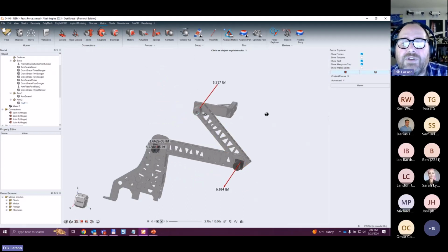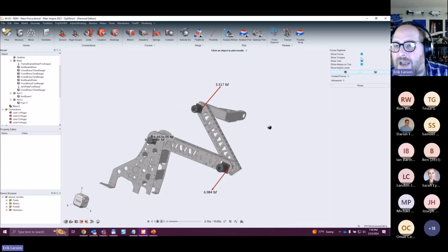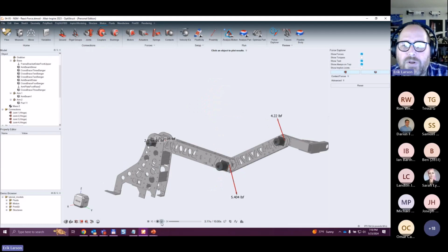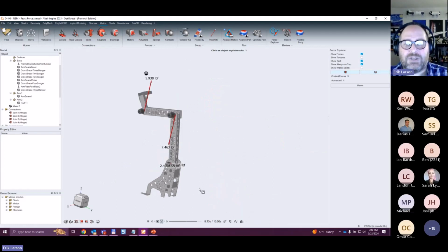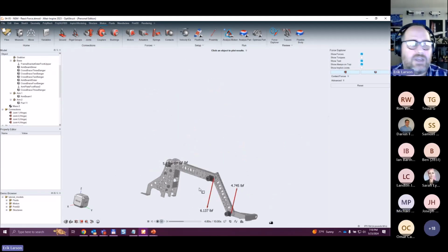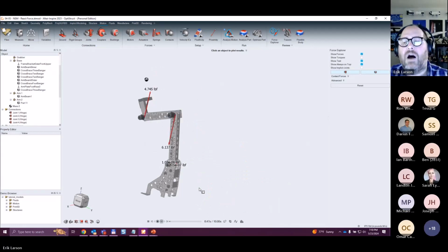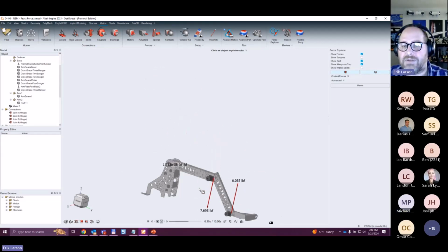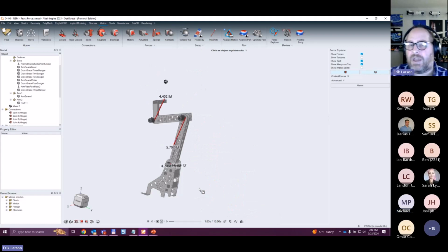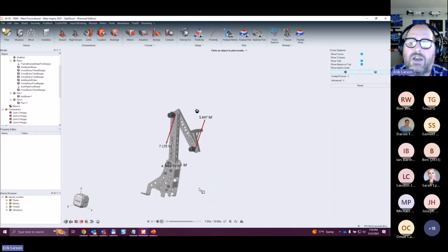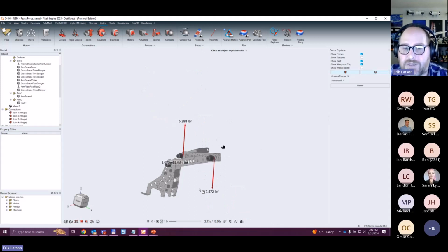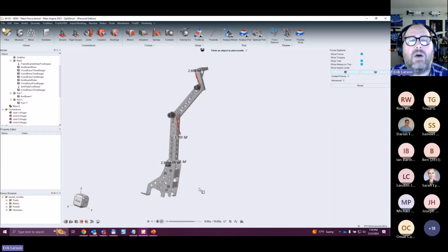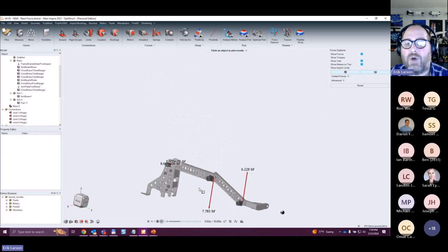And you'll see at every single one of these joints, it's telling me how much force is acting on that joint and in the direction that it's acting. And I can include the torques if I'm interested in those. And most importantly, it's going to change, so it's constantly analyzing it through the entirety of the motion analysis. And so at any angle, at any orientation, I can check those forces. I can use them to do an analysis or just find out what those forces are so I can be aware of it.